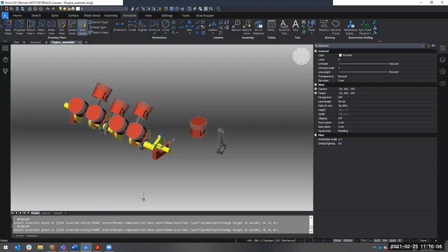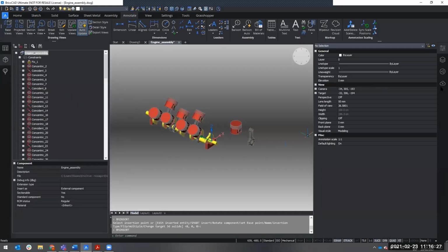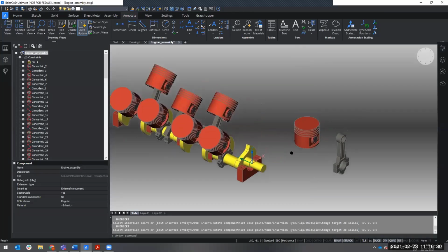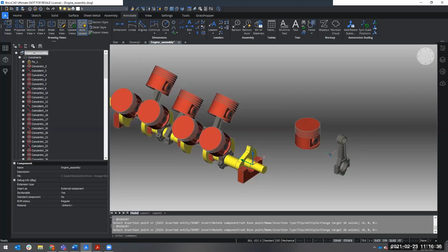And we are at step 5, and not every step of the way is explained here, but I will walk you through it, and you can have the recording of this part afterwards. So what we will do is use constraints, and there are already a fair amount of constraints. If you open the mechanical tab, there are already some constraints, and we will use these constraints both to place the elements as well as to drive or work together with the rest of this assembly.